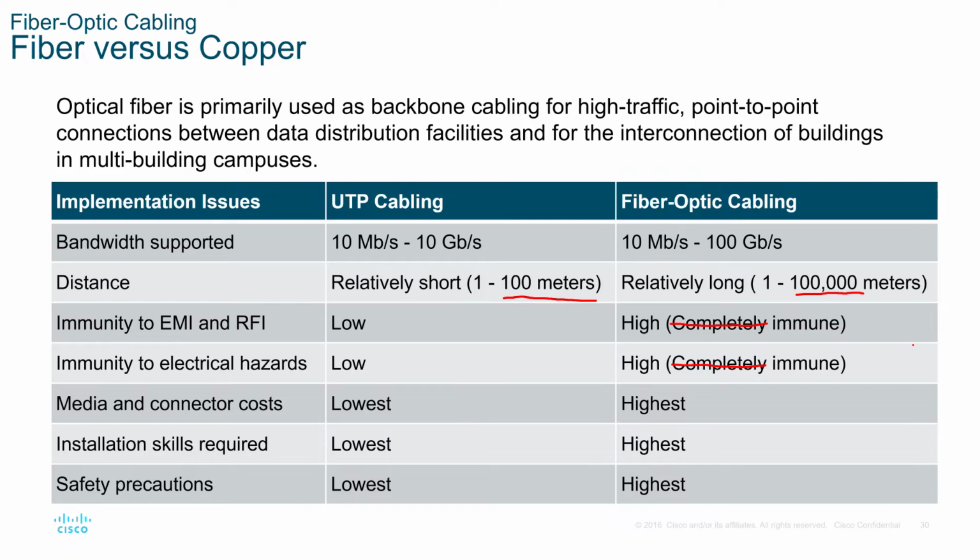It is, though, the connectors are high in cost. With the older technology, yes, it was a high skill requirement. And safety has to be high because, again, the light will damage your eyes. The fiber will go into your skin and you can possibly become infected. So the safety precautions that we must take dealing with fiber are much different than the safety precautions dealing with copper.